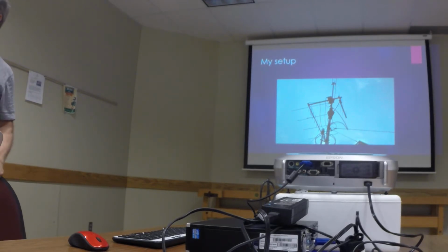So you normally work people north and south of you rather than east and west? Doesn't matter. As long as you can both see the satellite, you can talk. It's a lot like a repeater antenna 20,000 feet in the air. It's great. But again, you've got to get through atmospheric layers and water vapor, and on UHF that becomes a challenge without a lot of power.